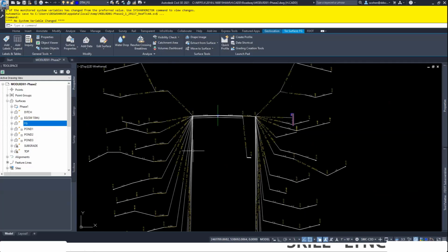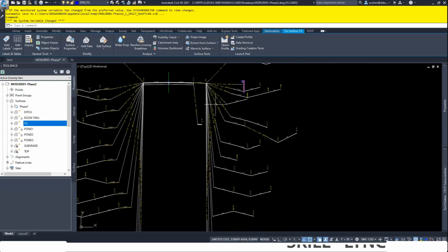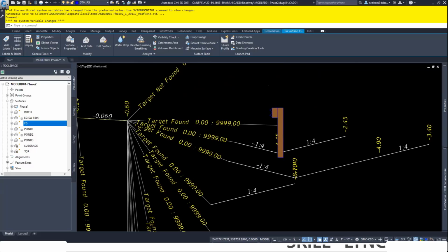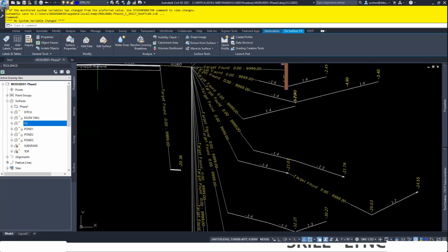Now, as you can see here, I had to add quite a few conditions because this project was kind of complicated. I had a berm in one spot. I had a pond in a few spots. I have special ditches that I have to follow. I also have guardrail, so I have to add guardrail, and I also have to add guardrail panels for the actual pavement, because in Florida they put a pavement panel where the guardrail is to support it better. Okay, so it doesn't erode the guardrail out.